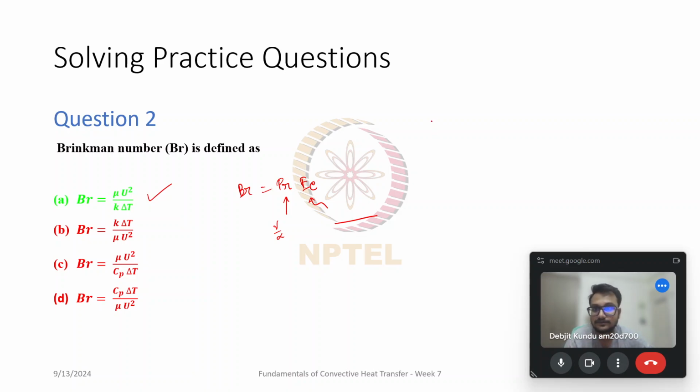So let's see, mu u square by k delta t is equal to mu over alpha times the Eckert number. So Eckert number, if we try to simplify, we will get u square by k delta t into alpha over mu.